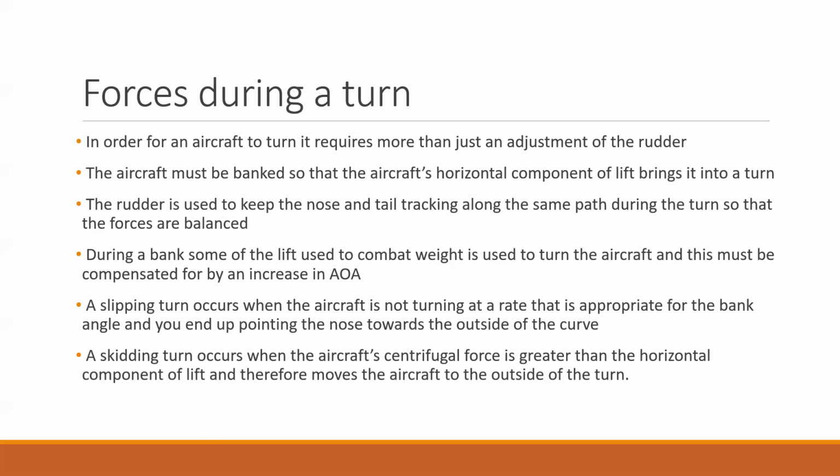And so the lift vector splits into two vectors. You have a horizontal component now, and you have a vertical component. The horizontal component is going to turn the aircraft in whatever direction you're wanting it to go. And when you create this horizontal component of lift, you also create another force, which is acting in opposition to it, and that is the centrifugal force. That's going to be pointing towards the outside of the turn, whichever direction that is.